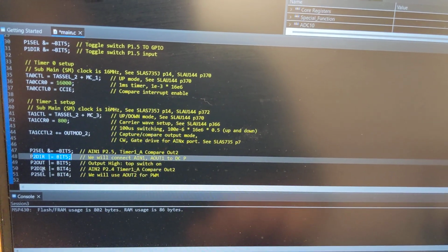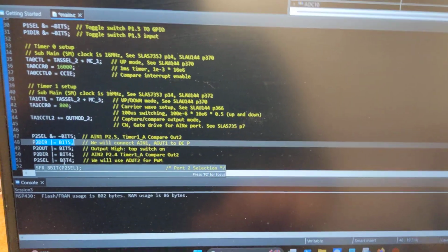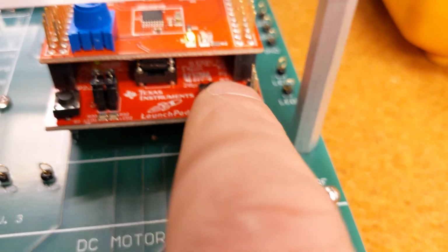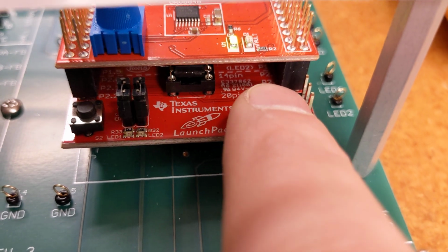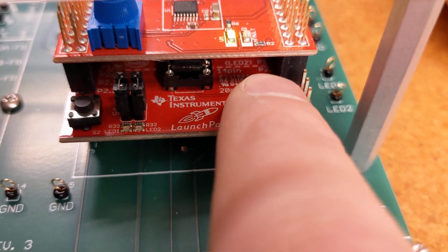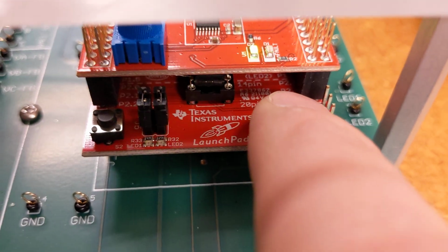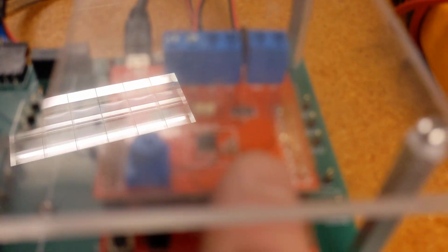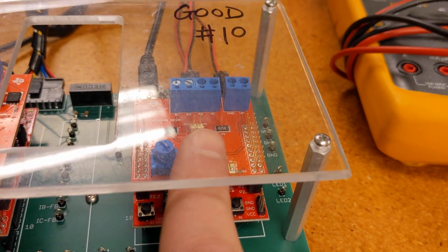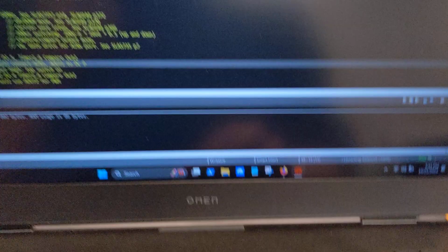And then analog out 2 is our bit 4. So coming down here, this bottom board, you can see it says P2, P2, P2. It's that one and that one. That's P25 and that one's P24. Those get fed into here, which then go to our analog motor out.